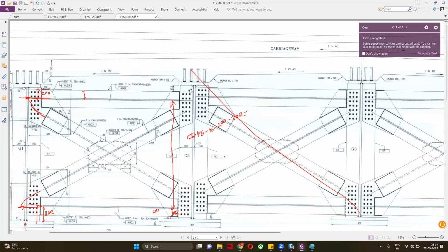First of all, your main beam resistance, because we have to check our web for shear and bending. Bending will be taken directly by the flanges, but shear will be there. That shear will be resisted by our bracing. So that is one case.